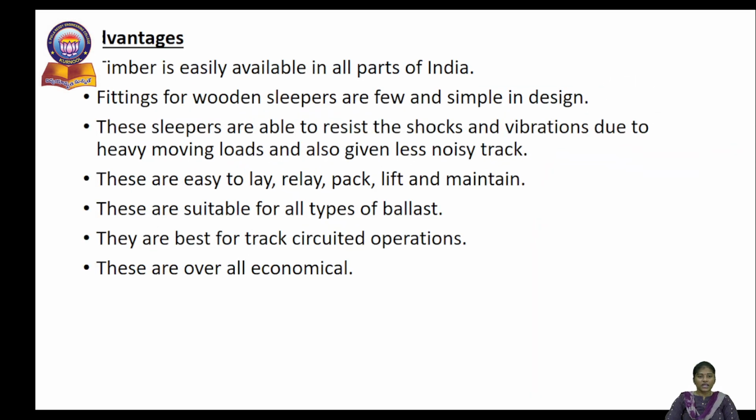So the main advantage with these timber sleepers is timbers can be easily available in all parts of India. Fittings for wooden sleepers are few and simple in design. These sleepers are able to resist the shocks and vibrations due to heavy moving loads and also give a less noisy track. They are easy to lay, relay, pack, lift and maintain.